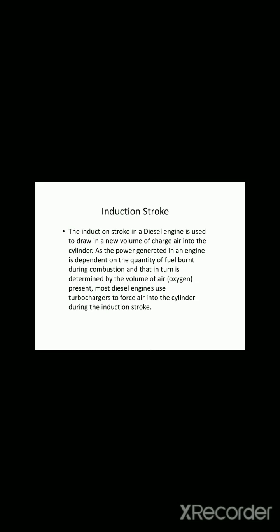Diesel cycle. In that particular diesel cycle, the induction stroke is available. The induction stroke in a diesel engine is used to draw a new volume of charged air into the cylinder. As the power generated in an engine is dependent on the quantity of fuel burned during combustion, and that in turn is determined by the volume of air, that is oxygen, present, most diesel engines use turbochargers to force air into the cylinder during the induction stroke.